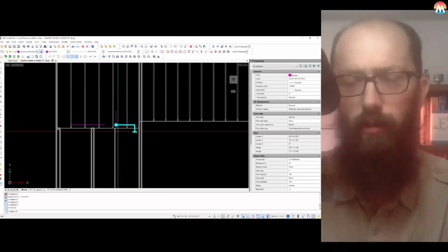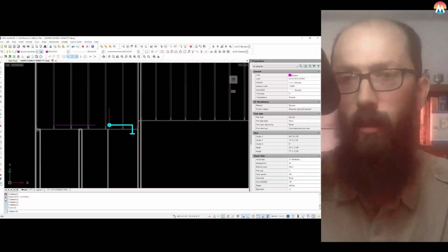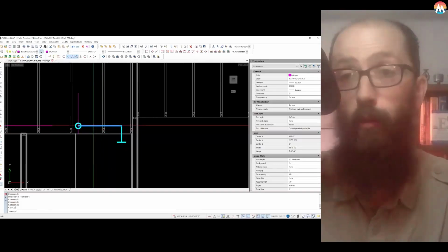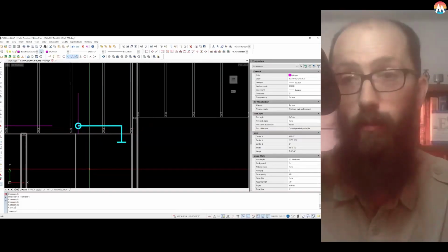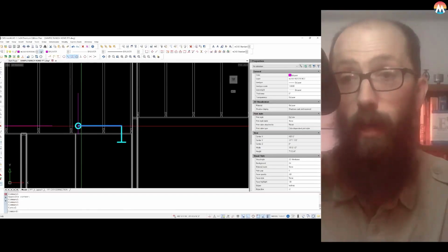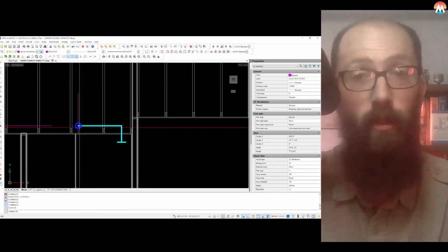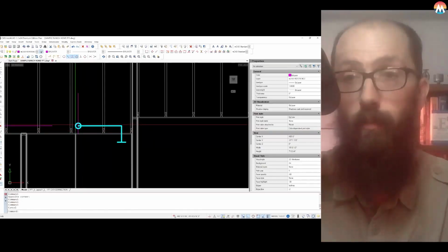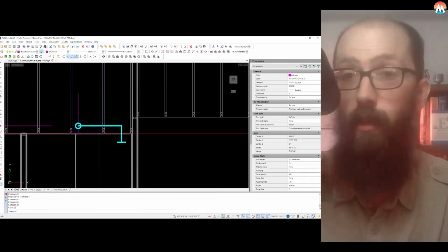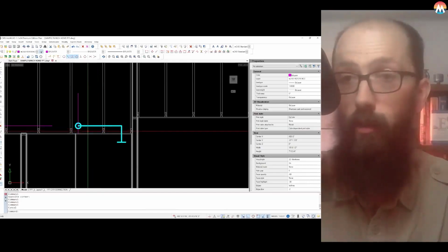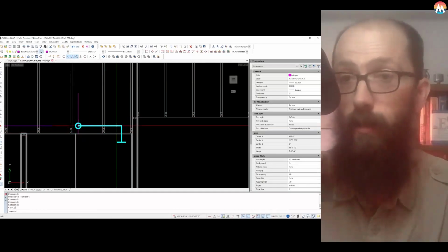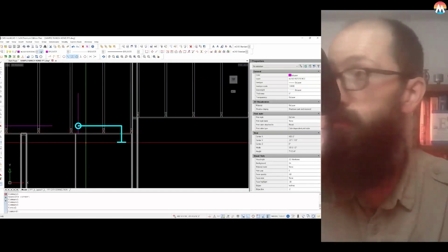I don't know if we've talked about tenting or not at this point, but tenting is something where you put visqueen over the pipe before you put the insulation in, so that the heat from the room as it's traveling up through the ceiling keeps the pipe thawed. There's water in the pipe. We don't want it to freeze. And so by covering it with visqueen before we insulate, ideally we're keeping any of the insulation from being below the piping, because we want it all above the piping. That way we create a little trapped area that retains the heat, and this pipe never freezes.